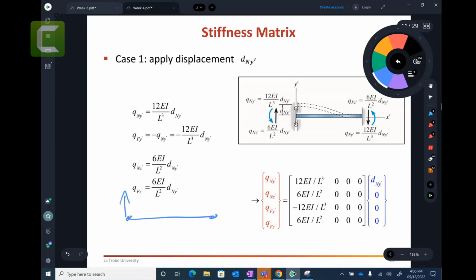It can go up and it can rotate. So there are a total of 4 degrees of freedom for each element. Right? Let's make it. So this is the beam element, and this point can go up and down, and it can rotate. This point can go up and down, and this point can rotate. So there are 4 possibilities that I'm talking about for the beam.